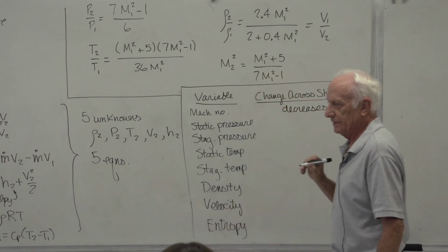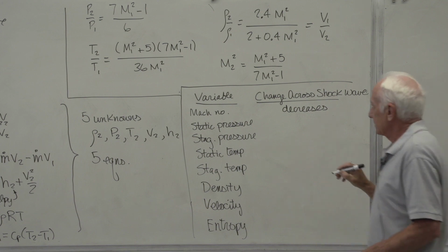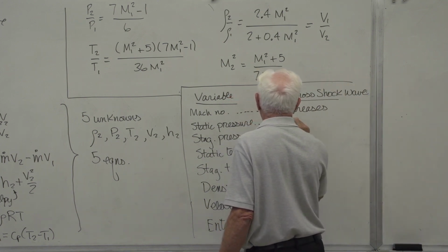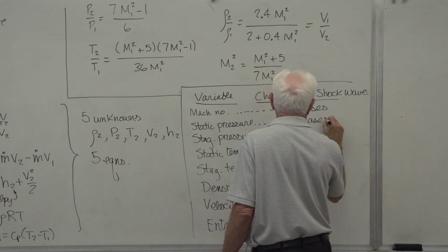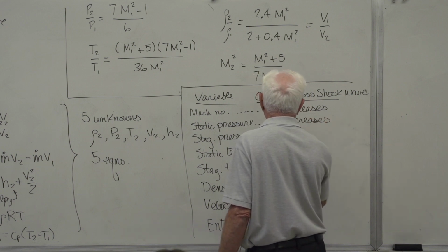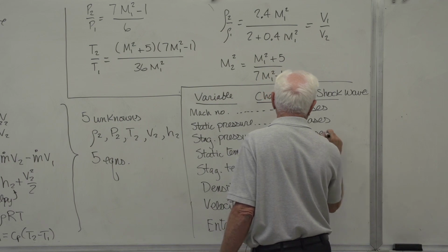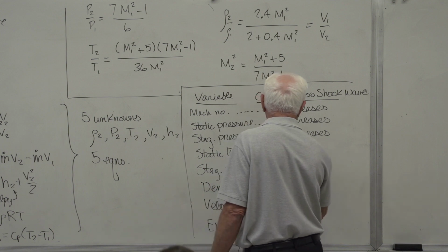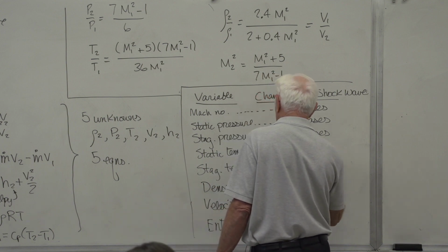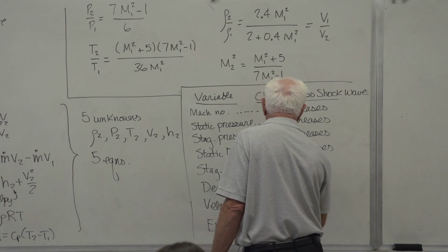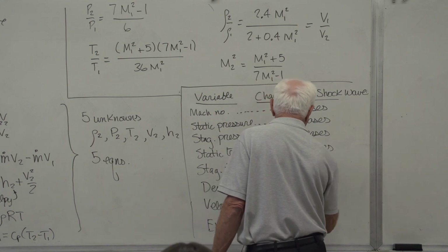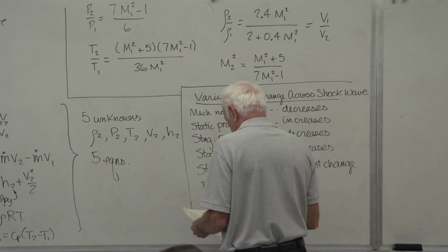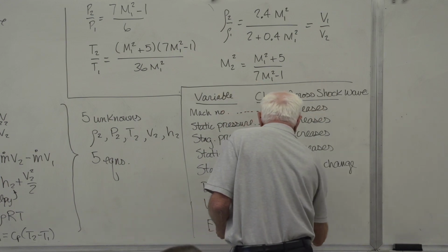Mach number goes down, decreases. Static pressure increases. Stagnation pressure decreases. Static temperature increases. Stagnation temperature does not change. Density increases.